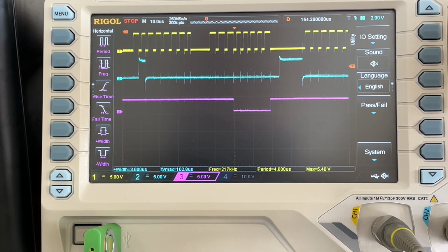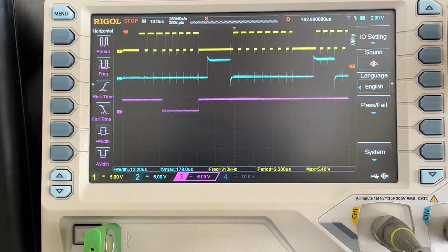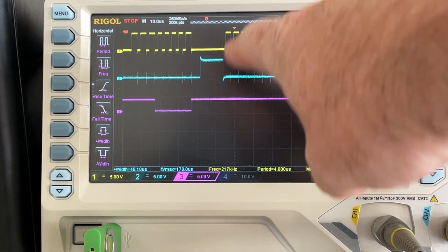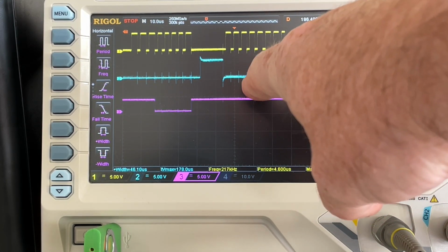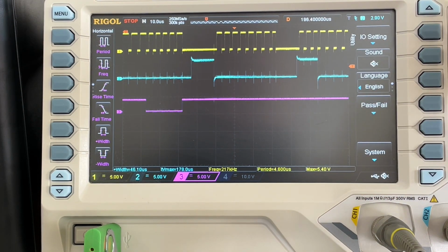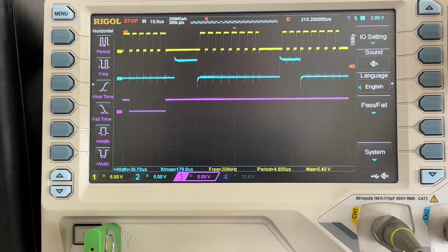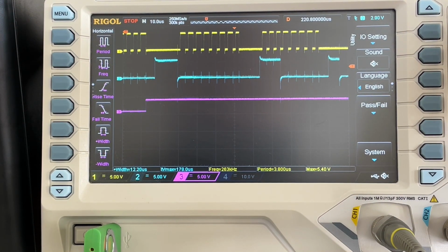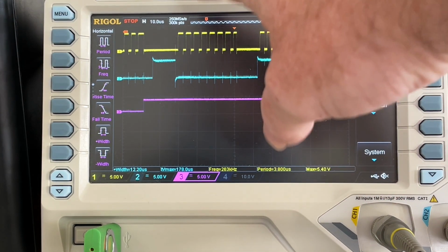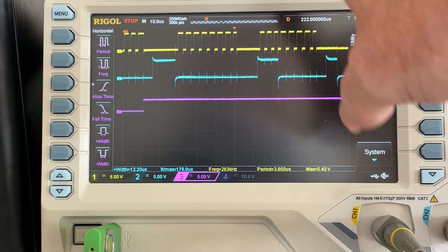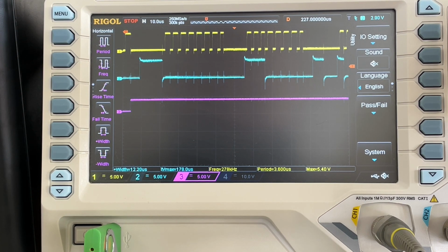If we scroll along some more, here I think this is the write command, and then this is the data to write back to that same register. So we read the value of the register, the program changed it, and then it sent it back. What this command is actually doing is setting cursor mode. It has to read the current text setup, then set the bit that indicates the cursor should be flashing, and then write it back. So we get another 2 bytes: write this register, and here's the data to write.